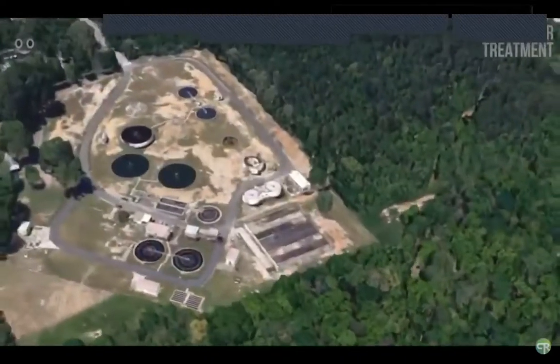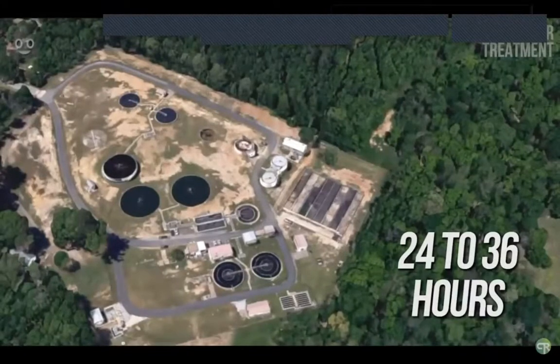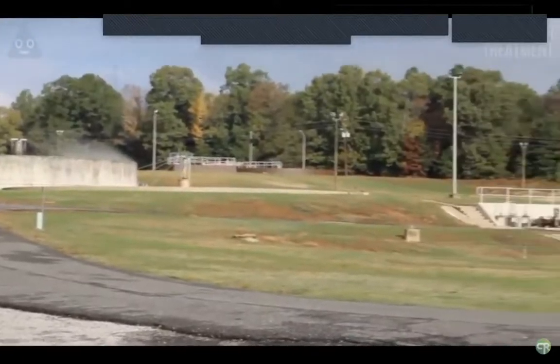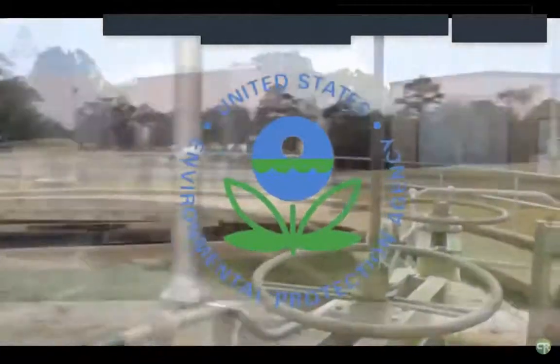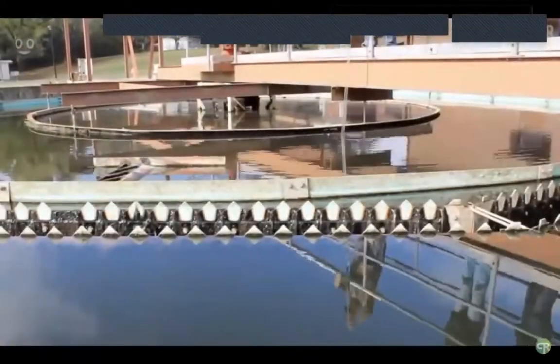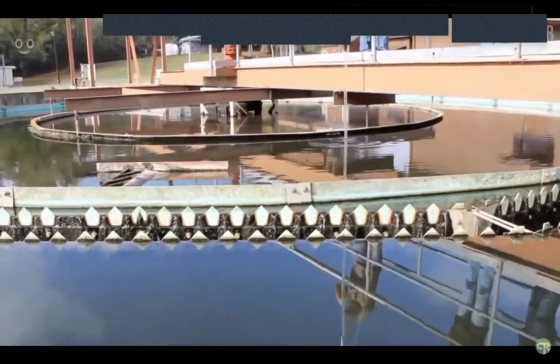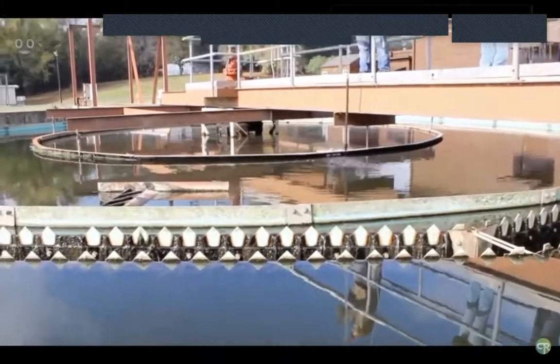The entire process of wastewater treatment takes on average 24 to 36 hours from when a drop of water enters to when it leaves. Each wastewater plant will receive a permit for flow rates, chemical levels, and effluent quality, among other things, from the EPA that outlines the necessary treatment for a plant. Wastewater plant operators will make adjustments to a plant's operation and constantly measure levels to ensure proper discharge and proper treatment.